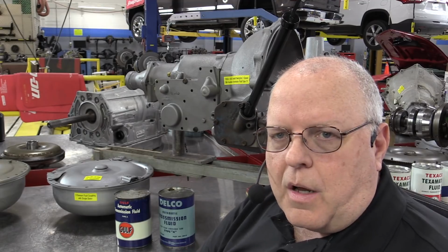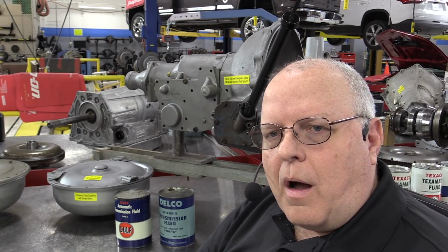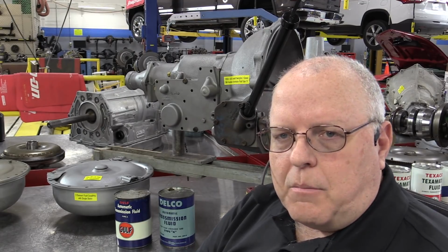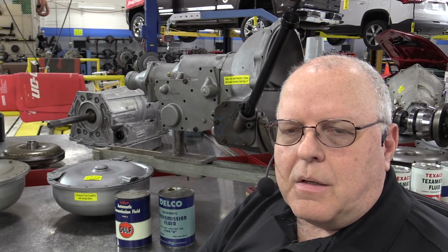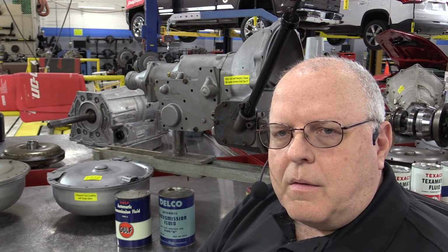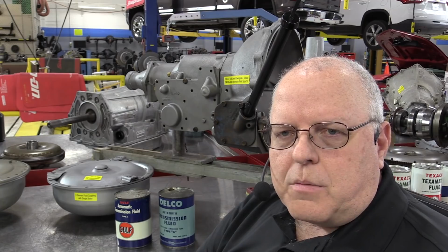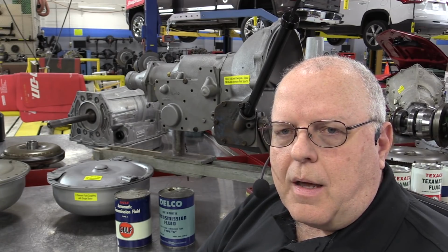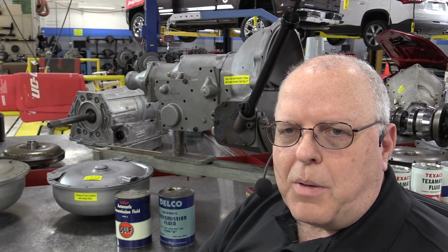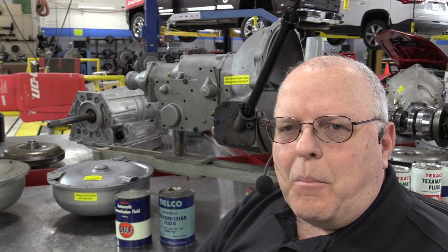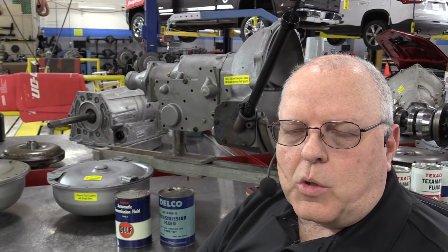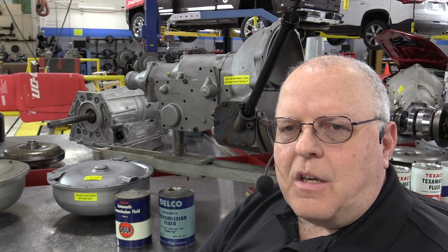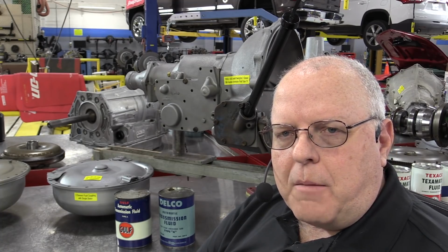Now this particular stator is made for high torque multiplication because it's just a 2-speed transmission. The stators used in modern transmissions don't need as much torque multiplication as the 2-speed Powerglide did. By the way, the higher the torque multiplication factor, the less efficient the torque converter can be.